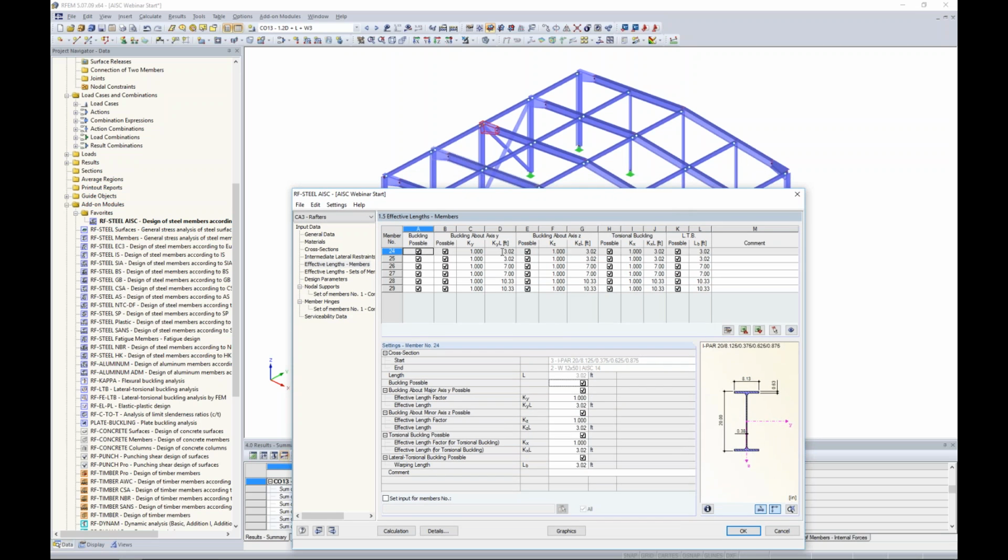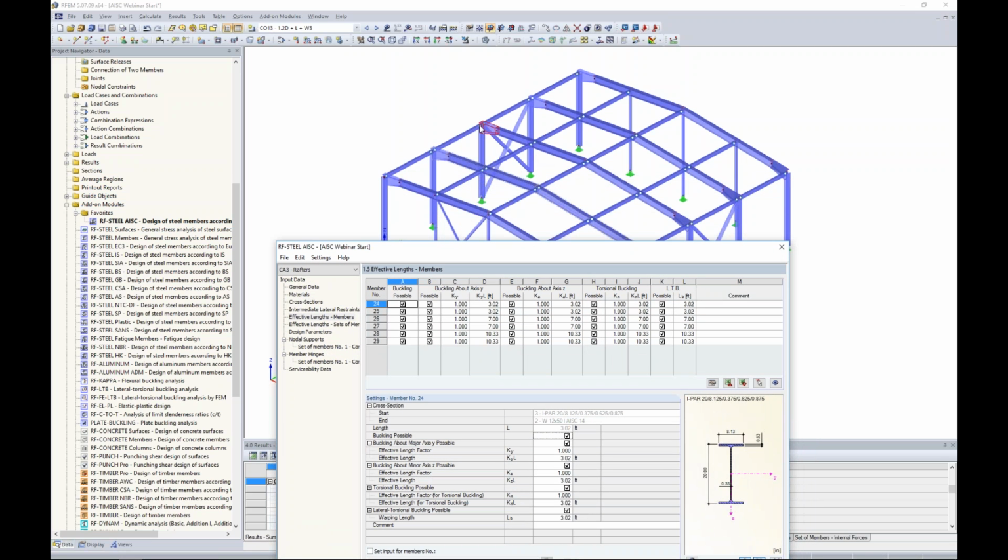You'll notice that this is a case once again where I really need to focus on these unbraced lengths. If I take a look at my little tapered member here, it's telling me that my unbraced length for my strong axis is only 3.02 feet. This is really wrong. My strong axis bending is actually the entire length of this continuous member, because I have nothing underneath it preventing it from bending in the strong axis. So actually what I want to set this as is 40.7 feet. You'll notice that when I do this, this K column automatically changes to 13.489.